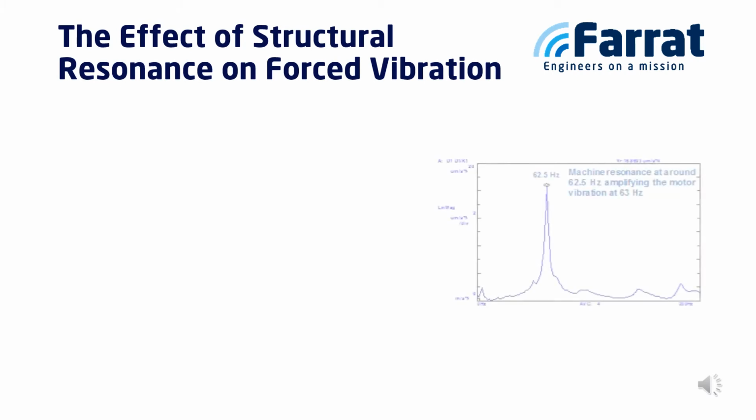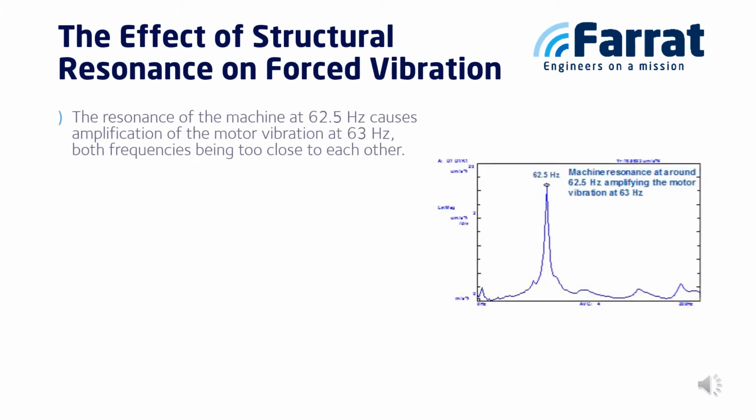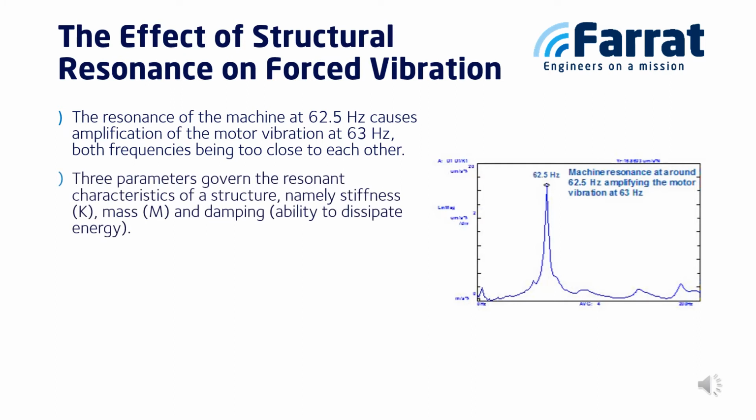What we're seeing here is the effect of structural resonance. On the example, we can see that the resonance of the machine at 62.5 Hz causes amplification of the motor vibration at 63 Hz. Both frequencies are too close to each other.